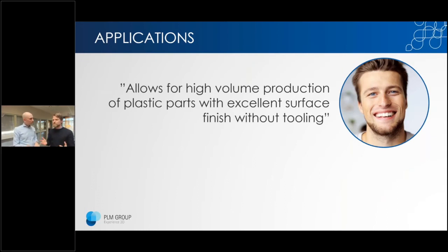So yeah, applications. Who would benefit from using SLA and DLP? Yeah, and it depends quite a bit because SLA, since it's been around for so long, you have basically machines starting from a couple of €1,000 up to like €1 million. Right. So the smaller ones are mainly used for prototyping, but there are other bigger machines used for production actually. So a really good application is actually in production. Because it allows for this pretty high volume production of high quality parts, and you don't need tools.